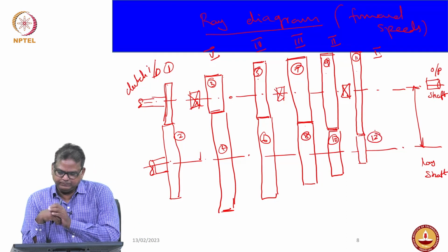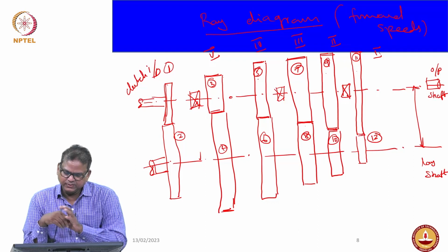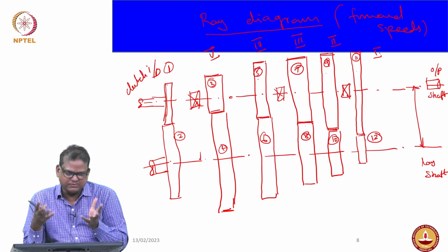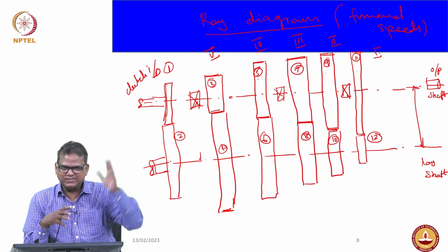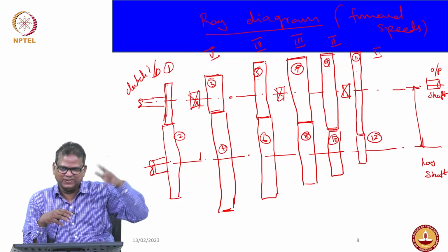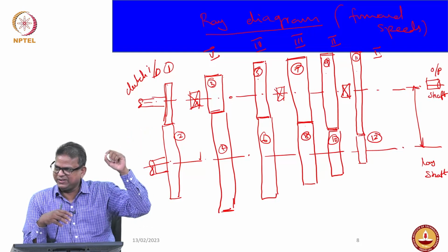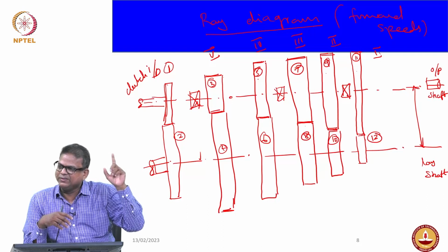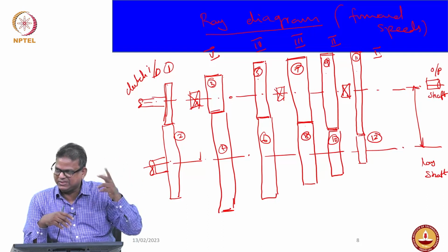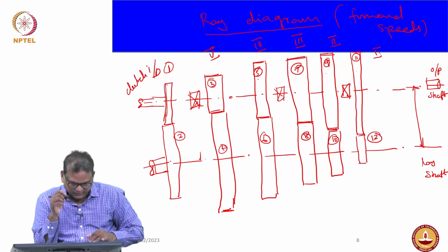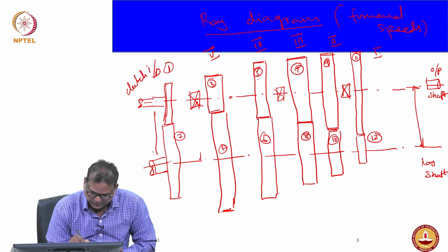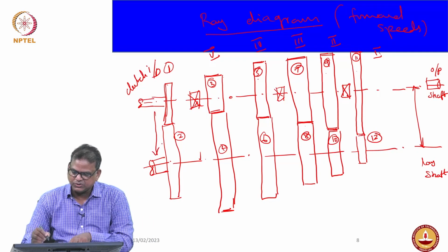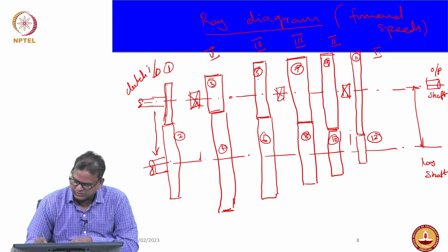Another question is, which are the drive gears and which are the driven gears? They systematically come in a machine tool gearbox. We take the odd ones as drive gears and evens as driven gears, but here that is not the case. The transmission occurs from the clutch input to the lay shaft. This is the one. Then from here the motion goes to your output shaft.